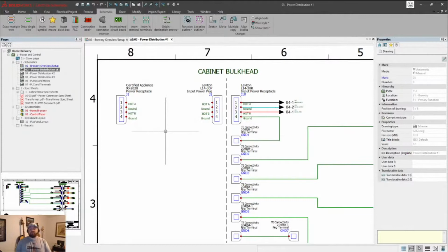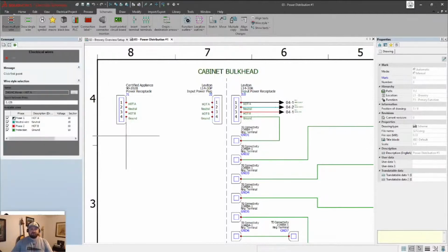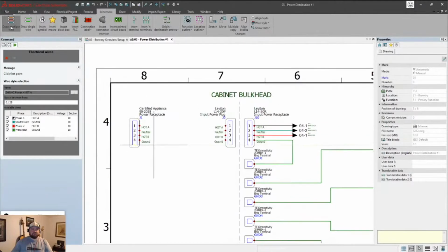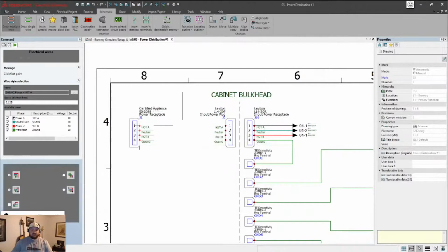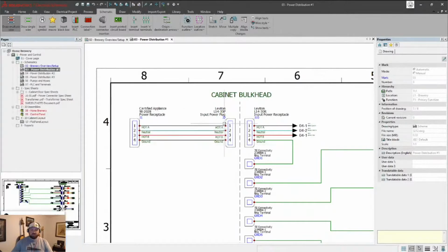And with drawing wires on a schematic, we have two different ways, right? If you're doing a lot more higher voltage, higher power kind of stuff, then maybe you want to draw something like a bus, and you can use multi-wire styles. In order to do that, I'm simply going to choose our multi-wire style, and I can drop it in place. Left click, and I've got it in place.